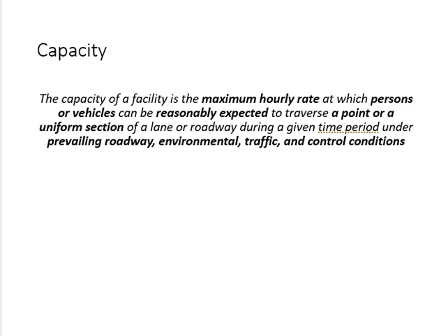Capacity, according to the manual, is not a fixed number. It's an expectation. If I do the design like this, I'm expecting I can have 2000 vehicles on the road per hour. This is an expectation. The actual can be a little bit more or less, and this is why they came up with the concept of level of service.